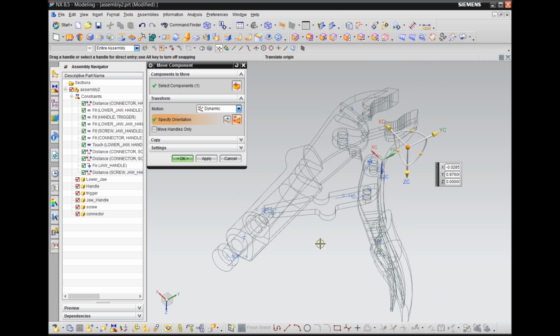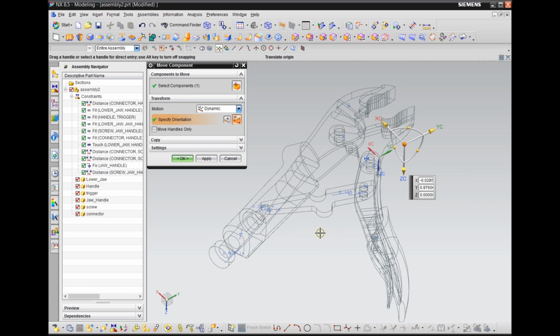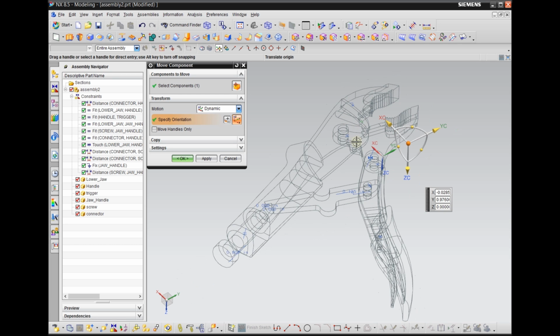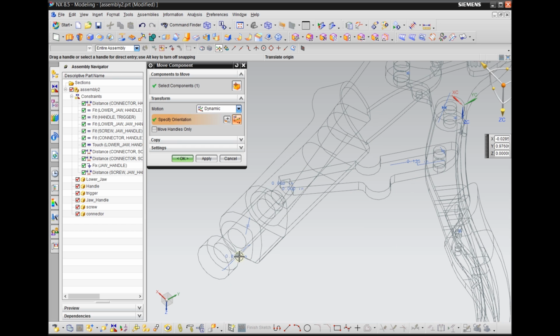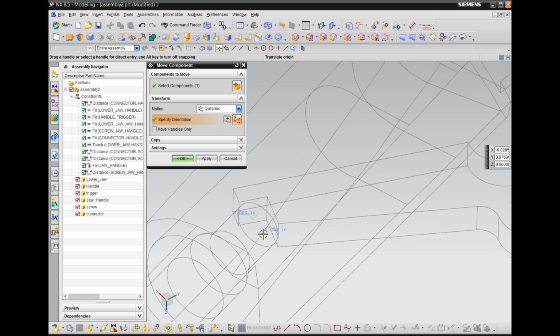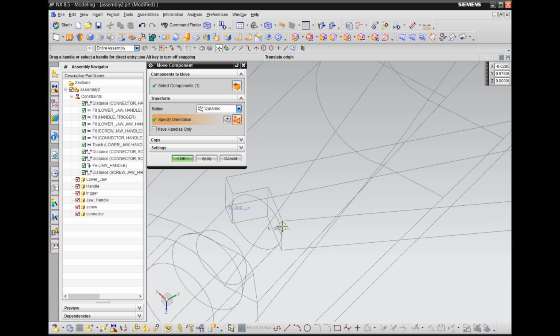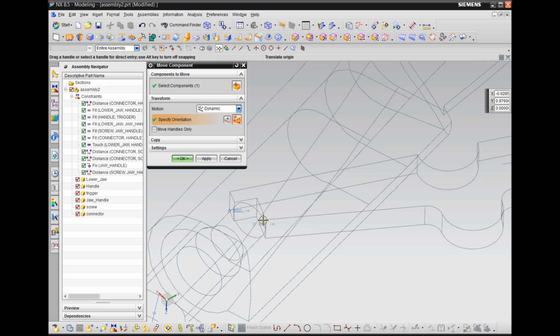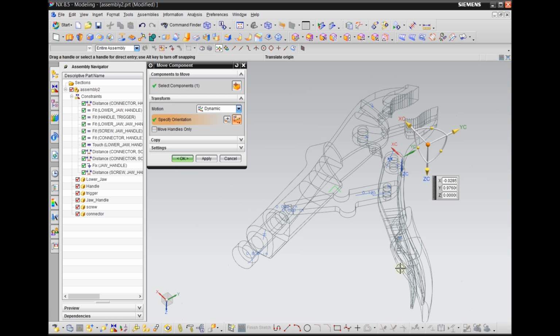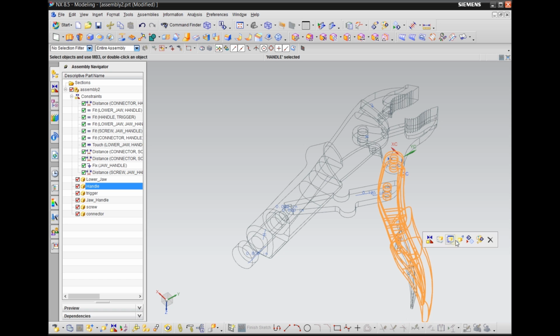So this will be good enough for your report, and you will need to add those fit constraints, and maybe you also need to add this distance to fix this nut, and probably you need that fixed constraint, and here you need these 2 constraints to make sure this corner rests on the tip of your screw. So let me keep trying to move this handle.